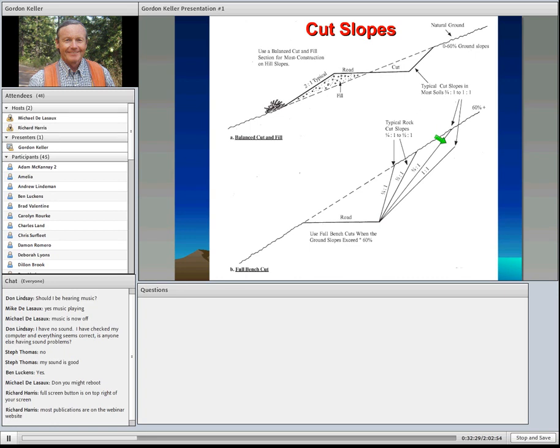And the other thing we want to do on construction, anytime we have a choice in slopes that aren't over, say, 50, 60, 65%, is try and balance our cut and fills, just because that reduces the cost of construction. You don't have in-hauling. You don't have movement of materials. So you're taking material from your cut here and putting it directly into the fill.